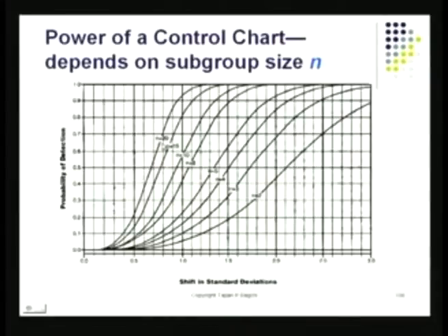This by far, what I am discussing, is probably the most complex part of control chart theory. So if you do not understand this completely, do not worry about it, but keep your N near 4, 5, 6 and let at least a sizable production take place, which could be after an hour or after maybe a shift or something like that, to collect the next sample.